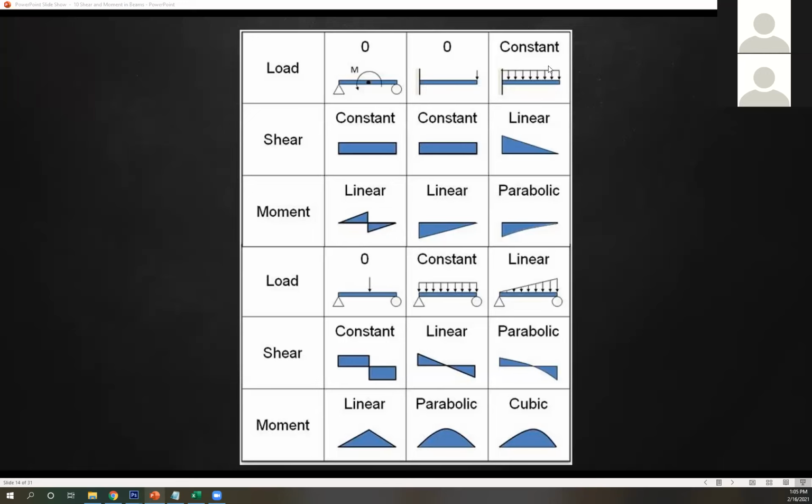Next, you have a cantilever with a uniformly distributed load. So again, you're going to have a shear force reaction and a moment reaction. So for shear force, your forces are downward, you're going to have an upward reaction. So go upward. You have a uniformly distributed load, 1 degree higher than that is a sloping line. Okay, so downward, therefore a sloping line downward, until you get your final point.